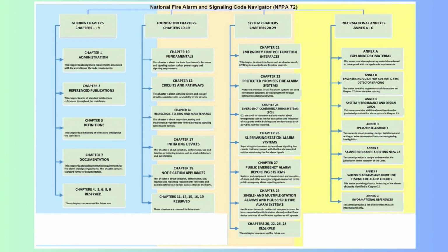Applicable codes. Identifies the codes, standards, and regulations governing the design and installation of the system, such as NFPA 72, NEC, National Electrical Code, and local fire codes. Ensures the system meets all legal and safety requirements. Inspection matrix. Details the required inspections and tests for the system, including pre-installation, installation, and final commissioning phases. Outlines who is responsible for inspections, for example, contractors, engineers, or fire officials. Ensures the system functions correctly and meets code compliance before approval. These sections are essential for maintaining clarity, ensuring compliance, and facilitating smooth project execution.